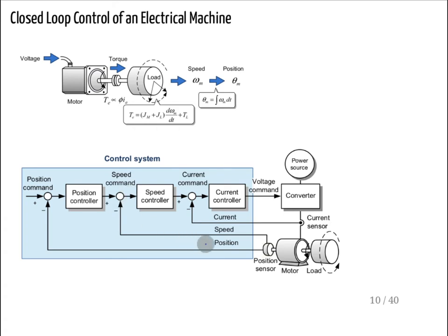So there are some kind of sensors, position sensors and speed sensors, and you have some either reference in the position, or you have some speed command, and then it just compares it with the actual position and speeds. Then you have the speed controller. So these are PI controllers, so you can actually calculate how much current should I give to the motor to produce the required torque.